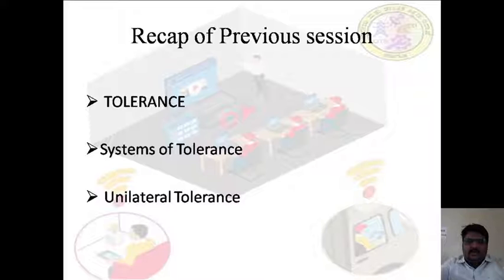This system is used in mass production when machine setting is done on the basic size. Whereas the unilateral system is preferred in interchangeable manufacture, especially when precision fits are required, because it is easy and simple to determine deviations.